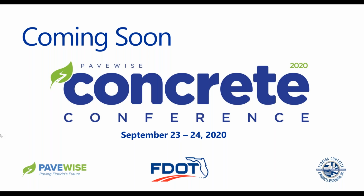If you're going to do it for northern states, see what the requirements are, because they may not allow certain soils. Certainly, you don't want a fine silt underneath your concrete parking lot in northern Minnesota. You'll get a bunch of heave. That's why they put foundations below the frost line up there. So I hope that answers the question. Look at what your local requirements are for base material.